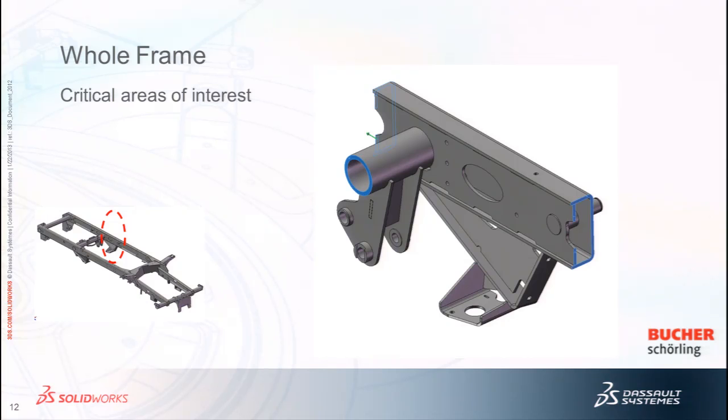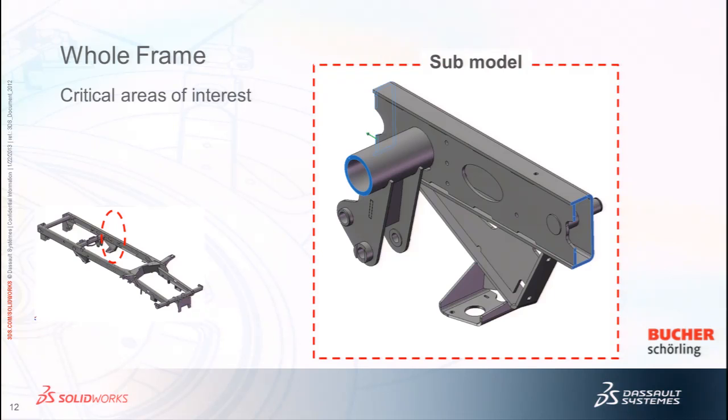The faces highlighted blue are the cut boundary, which is the boundary shared between this submodel and the rest of the assembly. So that's the cut boundary, and that becomes your submodel. This is where you would actually split your model. We don't have automatic splitting tools in the tool, but if you split the model, we will transfer the displacement, complex displacement fields at that boundary to the part, because you've already converged with the displacements.